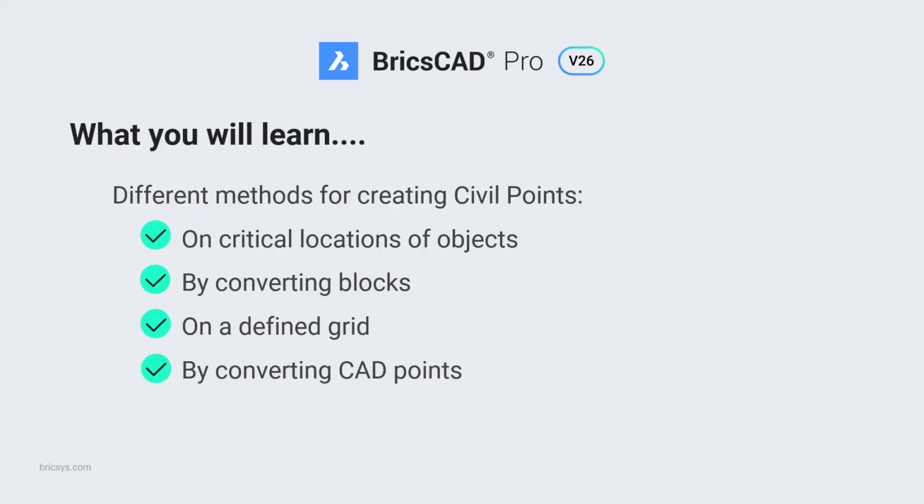BricsCAD gives you different ways to create civil points, depending on what your project calls for. You can place them right at the critical location of an object, convert existing blocks, generate them on a defined grid, or even just convert plain CAD points. No matter how your design is set up, there is a fast and reliable way to turn it into civil points. And in a minute, I'll show you exactly how easy it is.